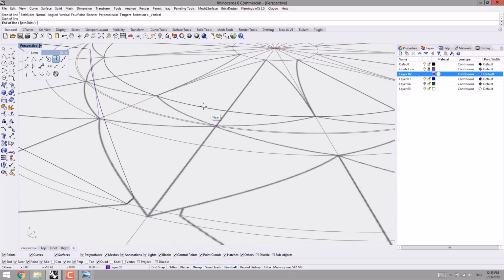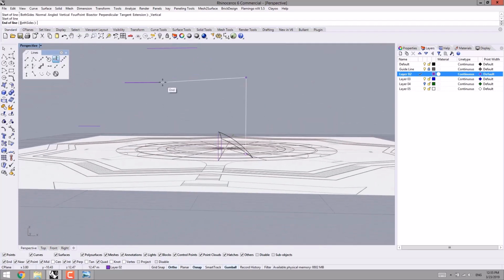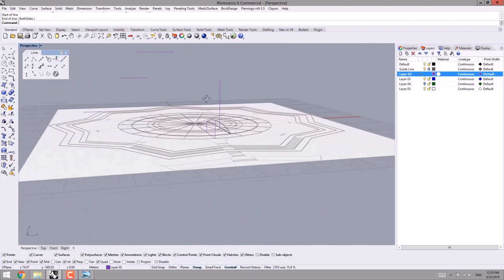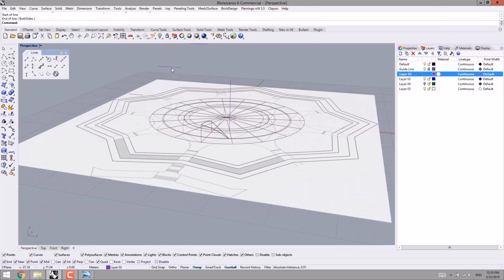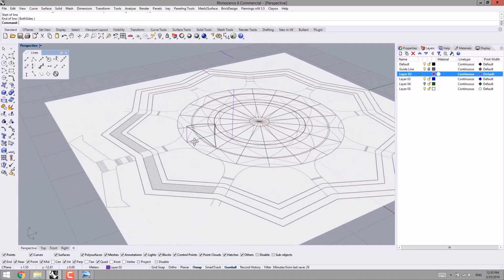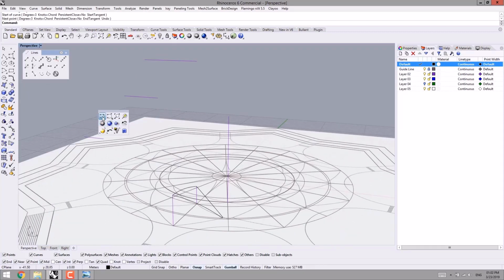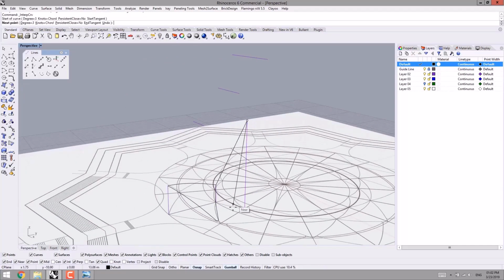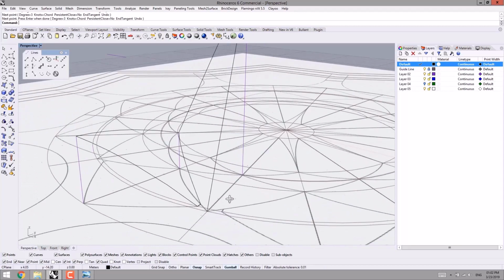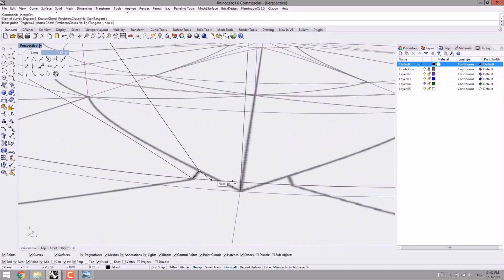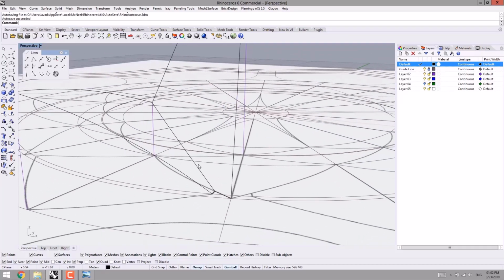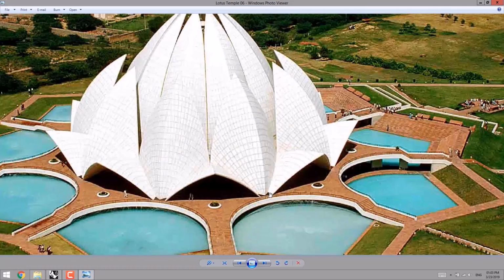For example, here at the intersection, and then I extend it till the second level. So I have sketched the vertical line based on the second level elevation actually. Following that, I select interpolate curve. I started from the end point, and then I extend the line to connect it to the ground or to the intersection, and then I sketch another line to connect these 2 points to each other. However, I can sketch it from here, the end intersection, and then connect it to the near one, so that we can adjust the top and front view.